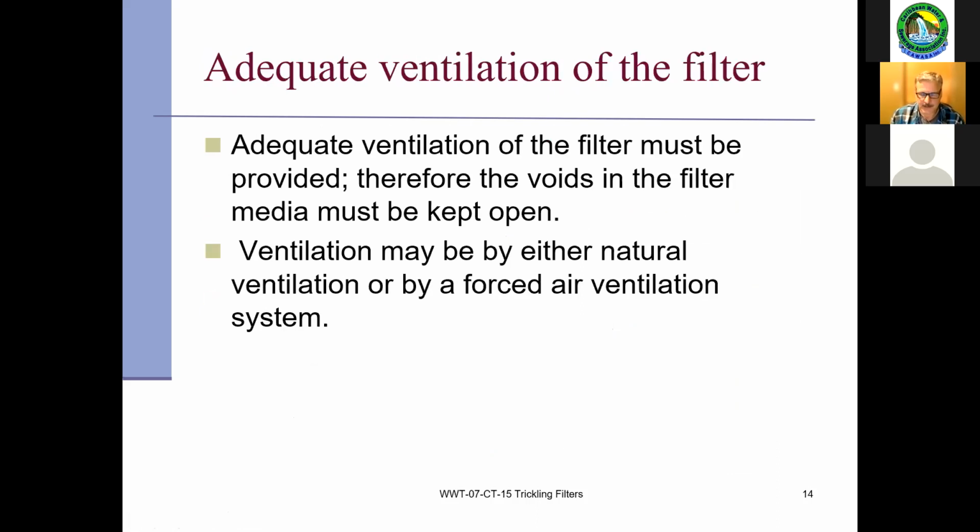Ventilation is key for these units. If trickling filters don't have proper air, a lot of them have natural ventilation. Some have forced air ventilation, so they would force air up through the bottom of the tank to feed that biomass. Without air, it's exactly the same thing that's going to happen in any other tanks. You're going to have sludge buildup. It's going to start decomposing, which is going to cause you a lot of grief.